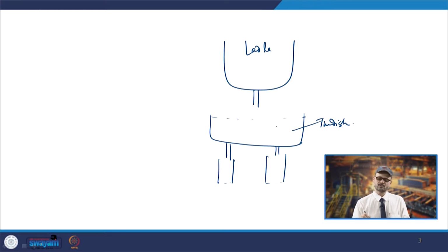Depending upon the flow configuration inside the Tundish, it will be desirable that they float towards the top free surface, where they are likely to be trapped because you have a slag layer. That may trap these inclusions, else they may go and stick to the walls, depending upon the conditions prevailing inside the Tundish.